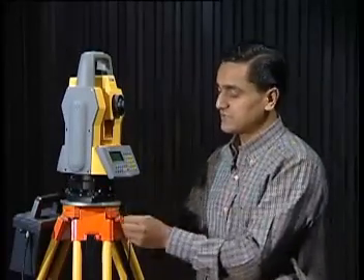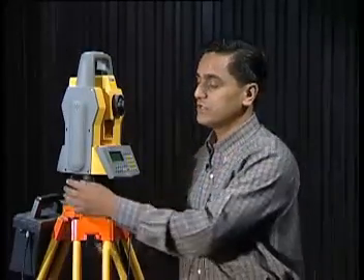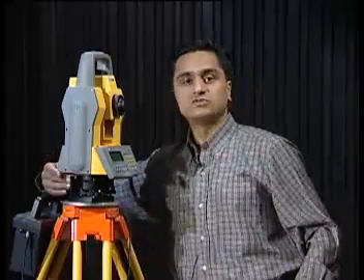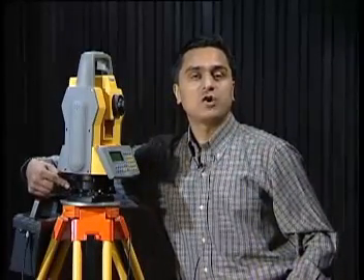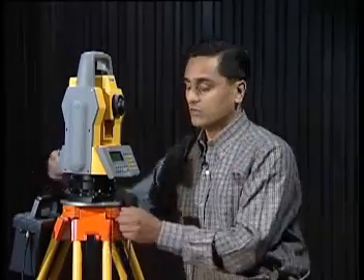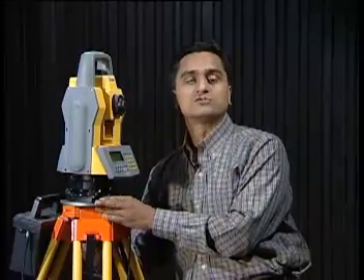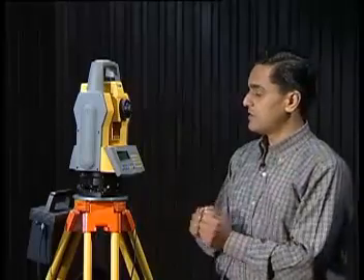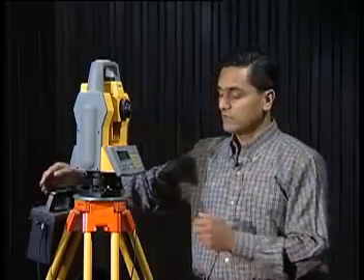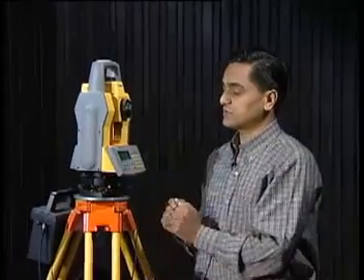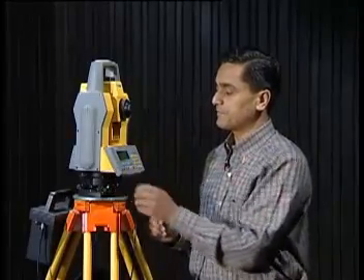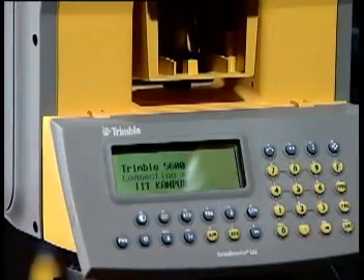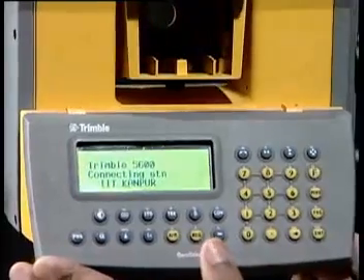Once it has been centered, we check the centering in the case of the total station using the optical plummet. The optical plummet is here. Then we clamp it. So now the total station is clamped and it's ready to work. Here is the battery and it is connected to the total station. I switch on the power. Now here in the panel, when I switch on the power,